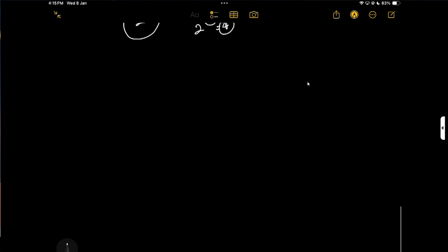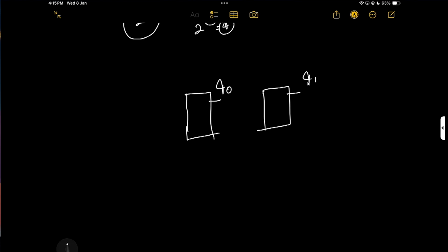So how do we make it? Two bits: one flip flop is here and another flip flop is here. I say this is my Q0 and this is my Q1. Here we take the T flip flop, because when the clock arrives we need to toggle. That's why the counter circuit will work. This is my clock, and T is always 1.